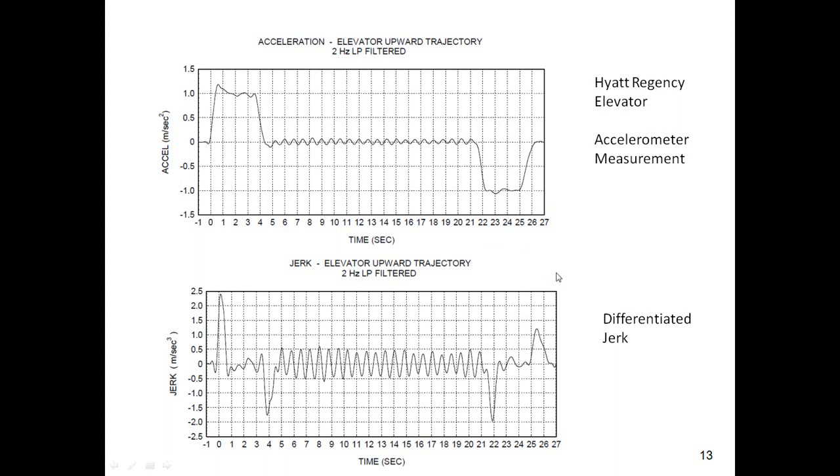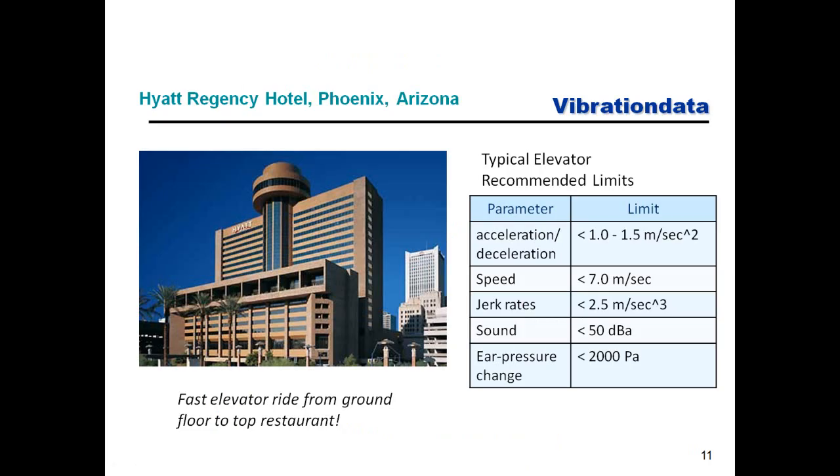I will mention that when I did this differentiation and processed this data, this low-pass filtering was a very critical parameter, because depending on how I chose that low-pass filtering made a big difference as to what this final level was. So I think that elevator society, and this is something I copied from the internet years ago from some long-forgotten website, I think what the elevator people need to do is put a rule of thumb for what the allowable low-pass filter is, or some kind of guideline. And maybe they did that, but I just overlooked it.